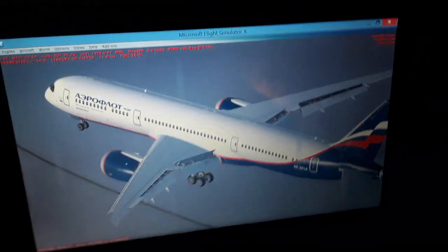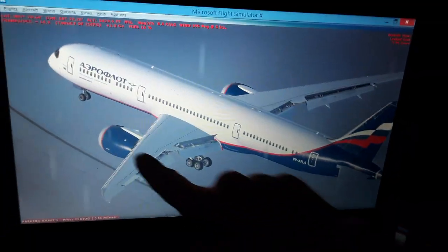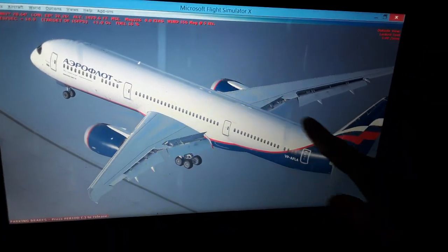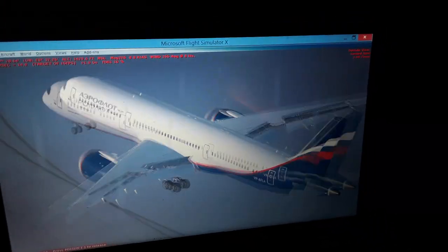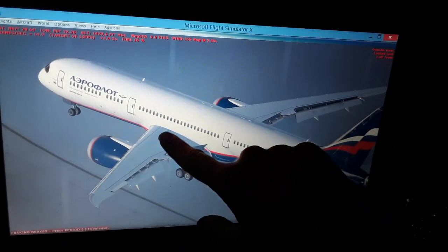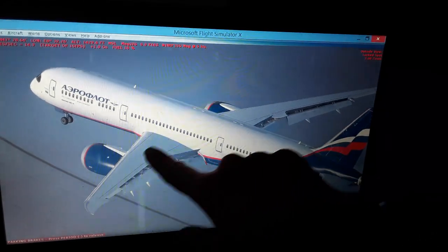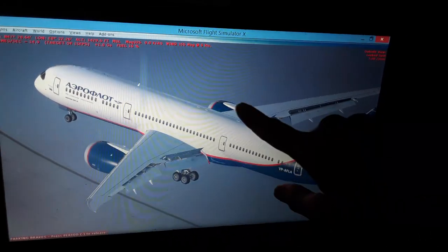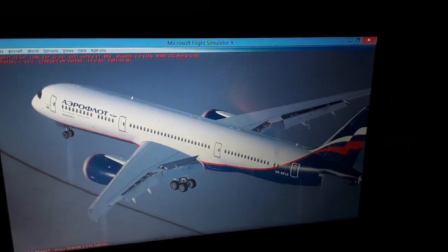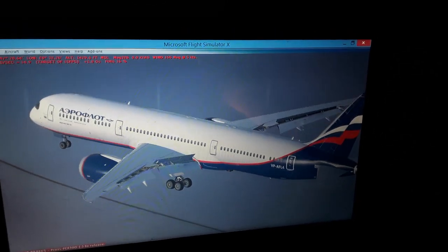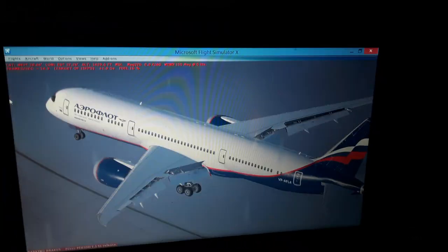So we have the surface area of the wings that hold the aircraft weight as we fly, using the aerodynamic lift. We have the thrust from the engines that move the aircraft forward. We have the mean aerodynamic chord position. The MAC is about 23% over here, where the maximum aerodynamic lift will occur in the forward wings. So also where the stall will begin, where the airflow becomes detached from the top surface of the wings. The stall begins is where we calculate pretty much the center of gravity, the vertical axis over here of the aircraft.